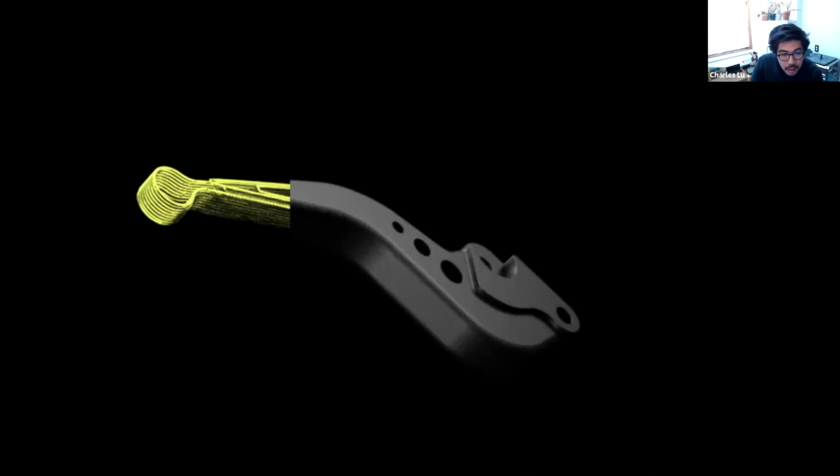Continuous fiber in a compliant mechanism. I would probably recommend our HSHT fiberglass. Although it is intended for high strength at high temperature, it is also a very rigid, robust material. For cyclical loading, you could use carbon fiber, but it is going to be a lot stiffer. So it depends what your use case is. I have seen internal use cases for compliant mechanisms, so reach out to us and we can see about getting you a sample part.